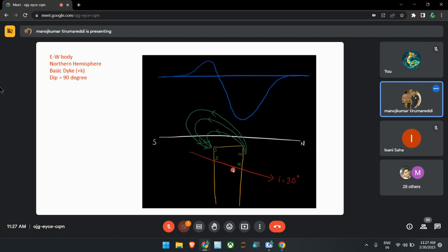Now coming to some intermediate latitude in the northern hemisphere. Why am I saying northern hemisphere here? Because we will get a different anomaly in the southern hemisphere for the same inclination. So here I will discuss the northern hemisphere first, and later we will go to the southern hemisphere. In the northern hemisphere, as I said earlier, the magnetic vector goes downward, I is equal to plus 90. Because of this, south and north poles will be induced like this.